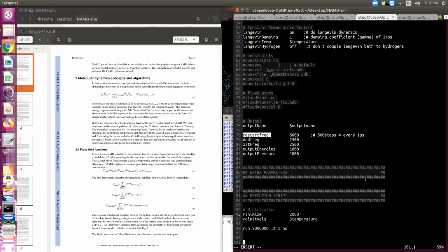While the simulation is running, if it crashes due to a power outage or something else going wrong, we use a smart way to save certain stages of the simulation, from where we can restart it. By doing this, we don't have to redo everything from step 0. So this is to save our process, from where we can restart our system in case something goes wrong. For now, we are setting the restart points every 5,000 steps.